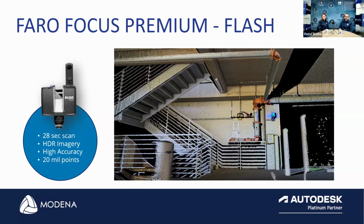Right. Just to touch again on the flash scanning, what you see there on the screen is an image taken from the 3D scan information from the flash scan. The flash scan does a 28-second scan with HDR imaging, with 1 millimeter accuracy like I mentioned, and you get 20 million points per scan. So there's a little bit of trade-off between speed and the amount of points that you can capture with flash scanning.